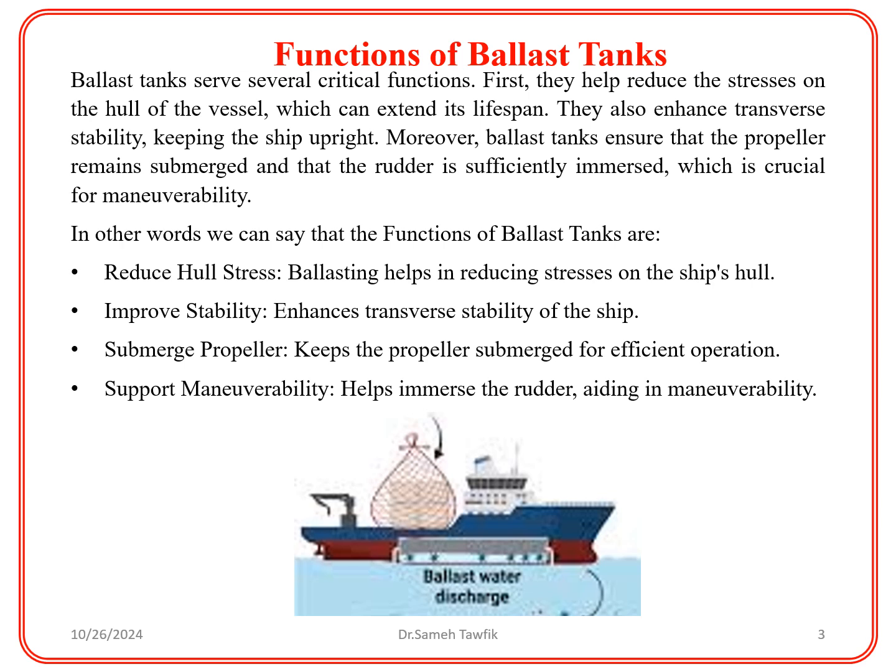Functions of ballast tanks. Ballast tanks serve several critical functions. First, they help reduce the stresses on the hull of the vessel, which can extend its lifespan. They also enhance transverse stability, keeping the ship upright. Moreover, ballast tanks ensure that the propeller remains submerged and that the rudder is sufficiently immersed, which is crucial for maneuverability. In other words, we can say that the functions of ballast tanks are: reduce hull stress.